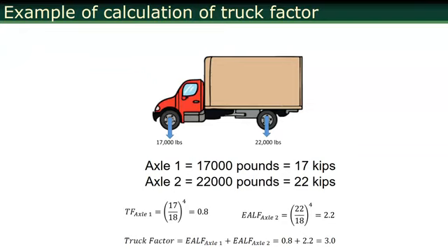So for fatigue cracking, regardless of temperature, see, pavement ME software includes the temperature fluctuations throughout the year, and it runs a layered elastic analysis. So this number is quite accurate, assuming that pavement ME software is accurate. We were expecting it to be not so accurate, but it is quite accurate for fatigue cracking, but not for rutting. We found that for rutting, it's not accurate. When you say damage, what do you mean by damage? If you're talking about fatigue cracking, this is pretty accurate. If you're talking about rutting, you really need axle load distribution done properly.